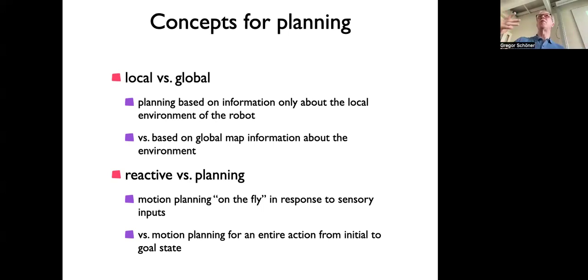And using the history of signals that you got, you can build a map, but that's a map only of kind of surfaces that would be local, because you don't get anything about what's behind that wall. You only get that when you drive around that wall. So you would be accumulating history information just to make the sensor information more stable, essentially something like a Kalman filter or probabilistic approach. But you could still do purely local planning, which is actually routinely done with these kind of systems.